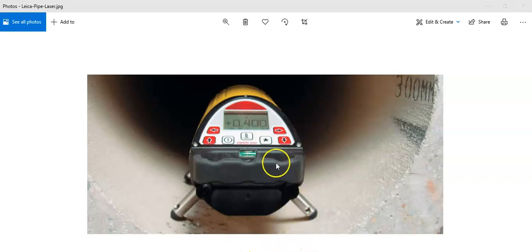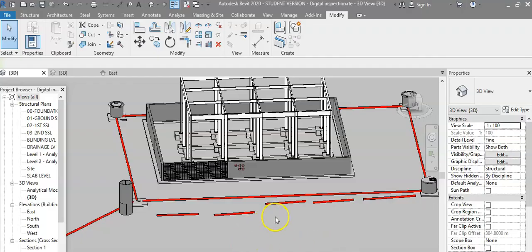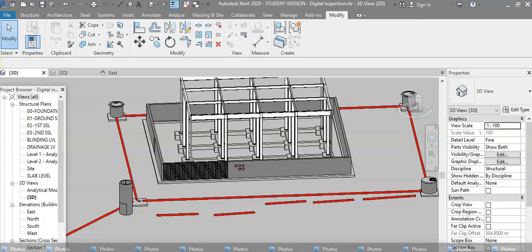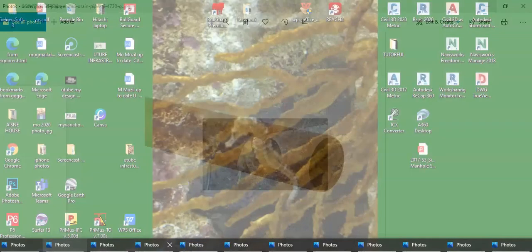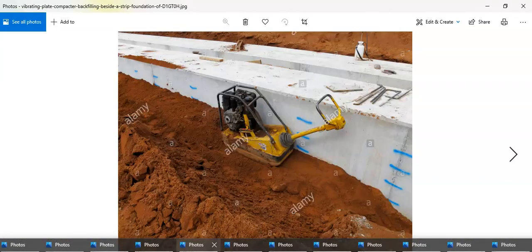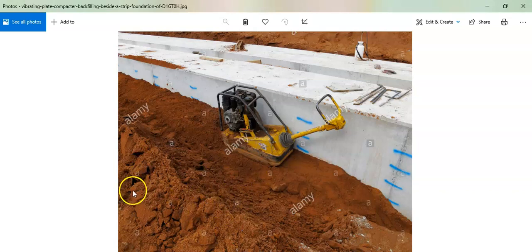So now we have an idea about how to use this instrument, and an idea about the type of materials, what type of pipes, the instrument, and now we can talk a little bit about how to backfill when laying the pipes, what we are going to do after we backfill these pipes. After we backfill, in some countries they use sand or the existing material, and we use this machine, the plate compactor or compaction tool, so that the soil doesn't become weak when building roads over this area where pipes are laid, and sink or start to crack here.